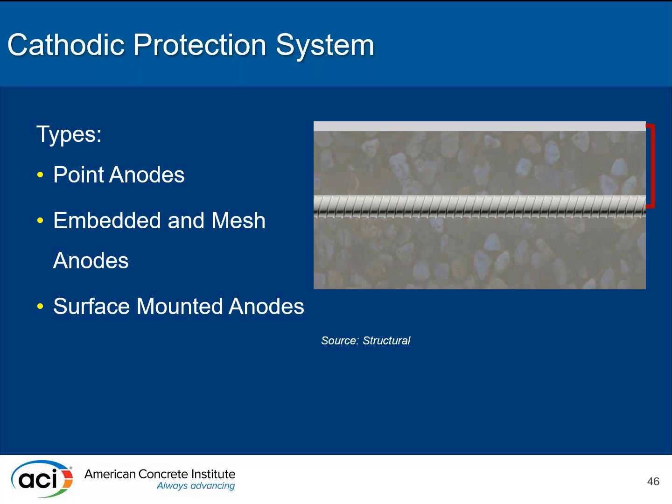Whereas surface-mounted anodes, where you have a metallic coating, tend to be more frequently used with an impressed current system. Though theoretically, they could be a galvanic system as well if you do a zinc spray on it. That actually happens. That's another way that you can see it. You have both as an option.